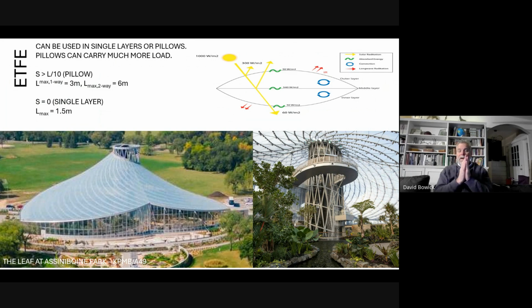First idea, orient the pillows radially. Sounds good, right? You start 3 meters wide at the perimeter of the building, because that's the maximum span. You're about 200 millimeters wide when you get to the core. They converge. You wind up with big triangular pillows. Not that there is anything particularly wrong with a triangular pillow structurally, but you can imagine that a long skinny triangle has twice as much boundary for the same surface area.